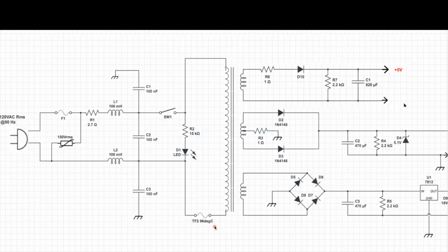Anybody ever work on an old computer and when you open it up, it's full of dust? Well, there's a condition where a fan is sucking in air to cool things, but now it's all clogged up with dust and dirt because it's many years old. Is it properly cooling? It's no longer properly cooling. The vents are blocked up with dust. So here's a situation where the overheat or thermal fuse might fail and protect us. Industrial equipment might have a thermal fuse in it.